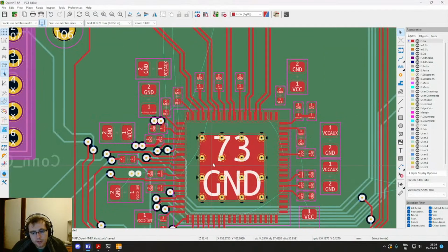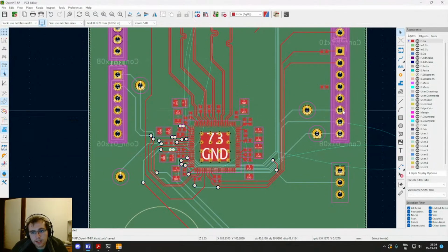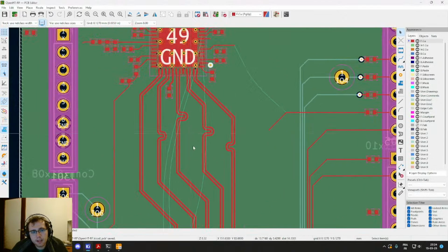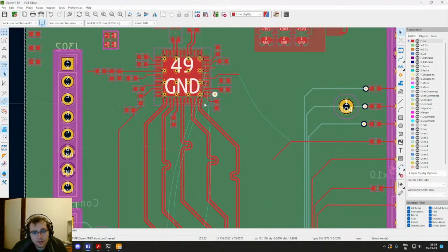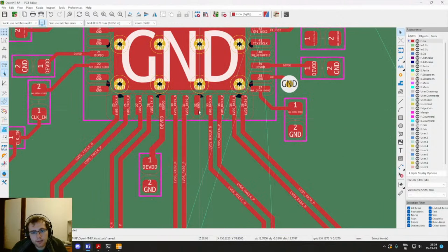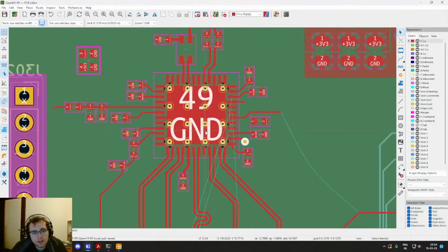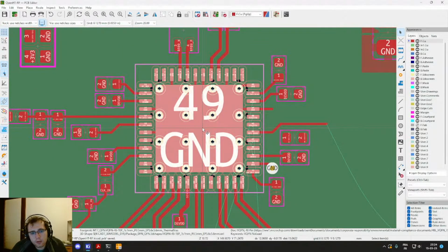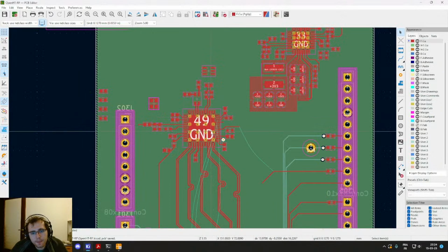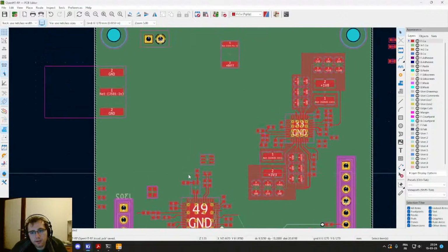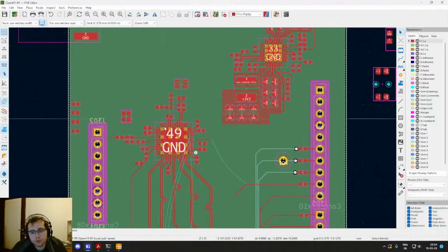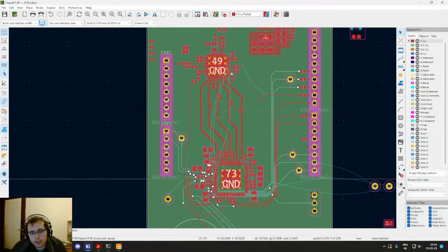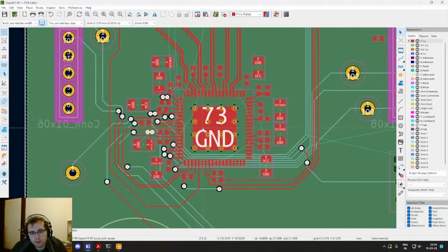Okay, so we routed the GPIO signals today. We routed the LVDS pairs. We had some fun with the wiggles and the length tuning, which is great. Next time I think we are gonna route the rest of the transceiver, maybe the RF signals, and then we will have to do the power. Power can be quite finicky because this needs to be well done too if you want clean power without too much noise and so on.